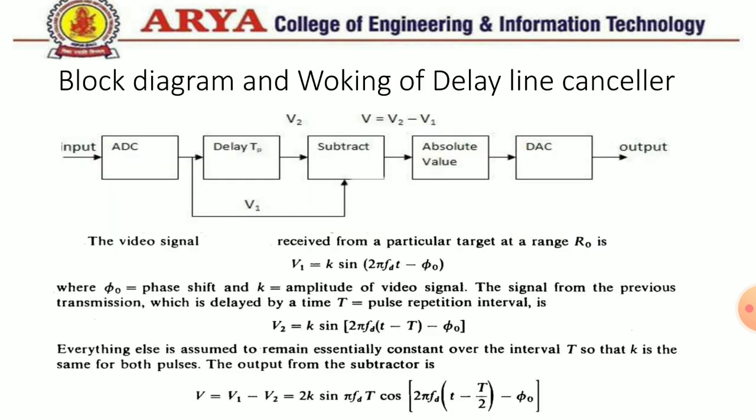Block diagram. Here we have the received signal of the radar at the input, and that is provided to a delay line, and that delay line is based on the pulse repetition frequency. So a delay of 1 by pulse repetition frequency is provided, and that is subtracted from the original signal. Ultimately we have a resultant signal with elimination of clutter, the low frequency components.